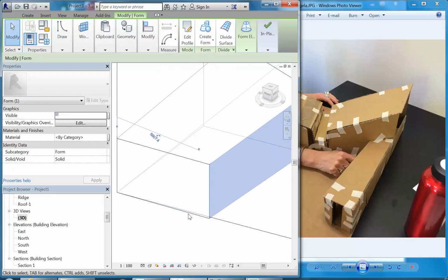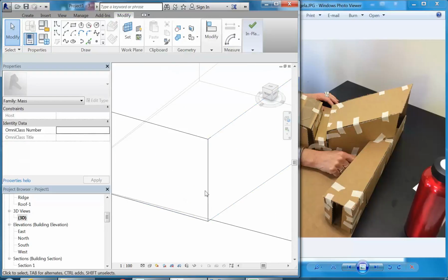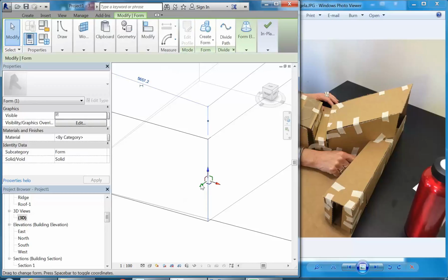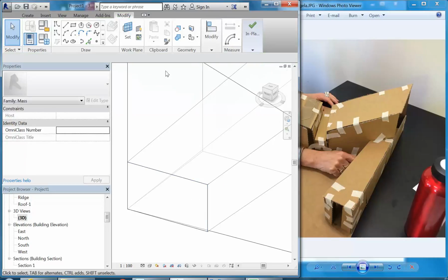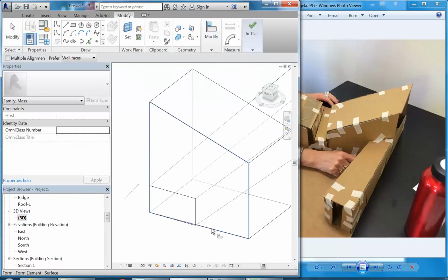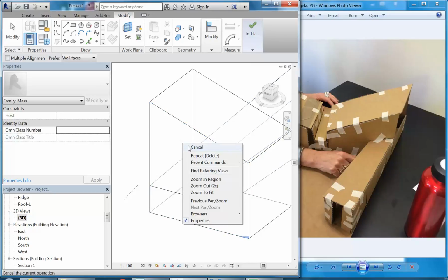Using the edge there, there's a few options, but just using this edge, I should be able to drag it and get that to align with this point here. Actually, without a plane, that can be tricky. So the other option would be to use a line and choose the surface there on the outside, and then just choose the surface at the end there, and that will line up exactly. So that's probably the best way.